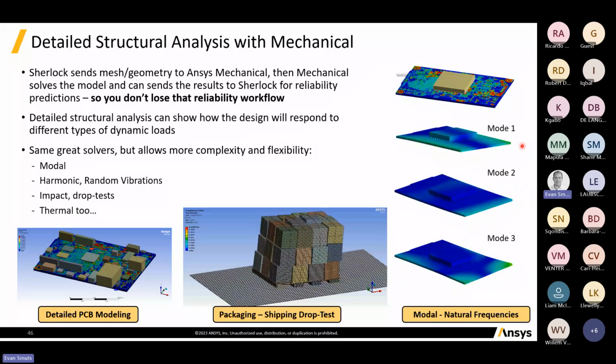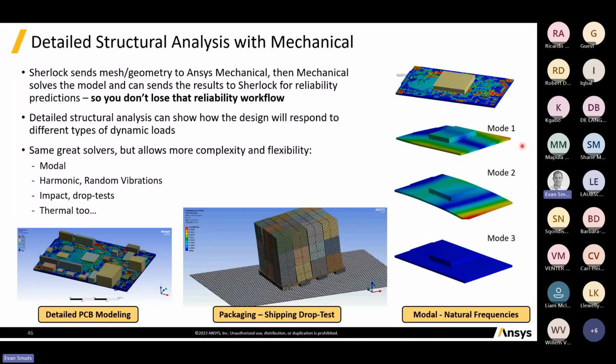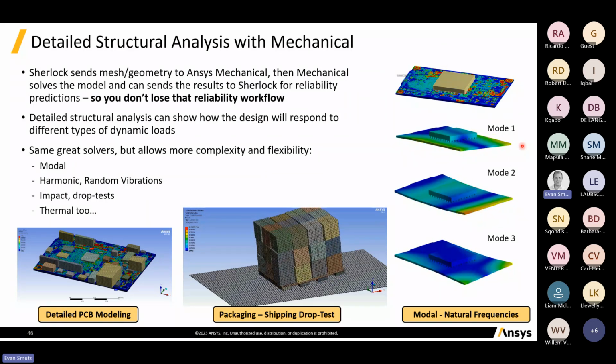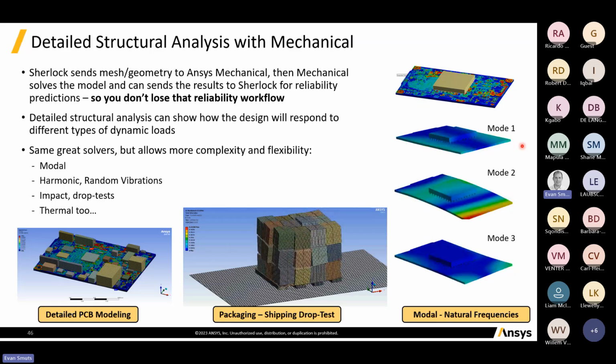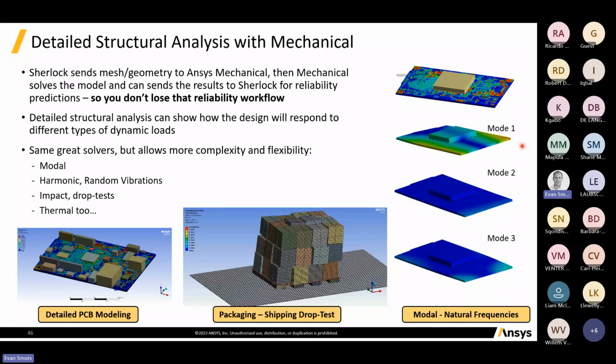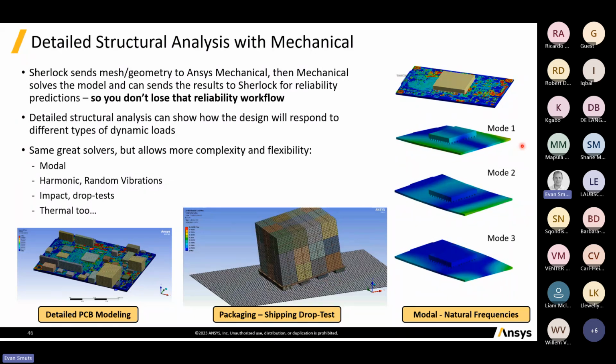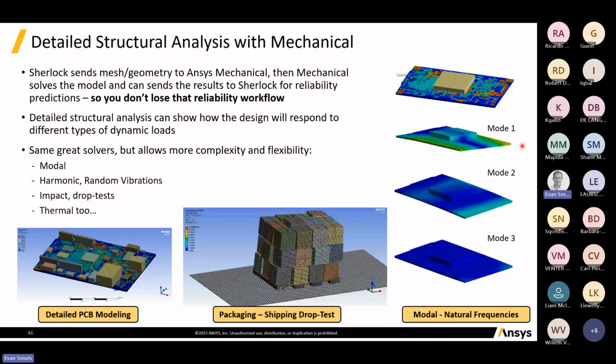And what many people don't know is, as much as we do these types of analyses in Sherlock, we can do basic modal, harmonic vibrations, impact tests, and so on. Much of that is actually run by Mechanical. It's actually using the Mechanical solver in the background. So in that sense, we can trust the results that come from Sherlock. It's based on a detailed, proper physics solver in the background.